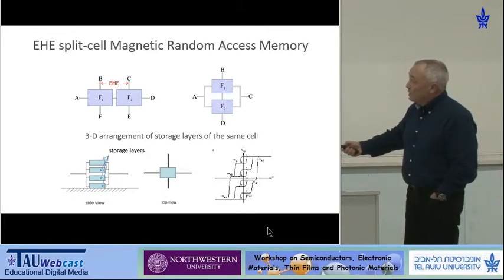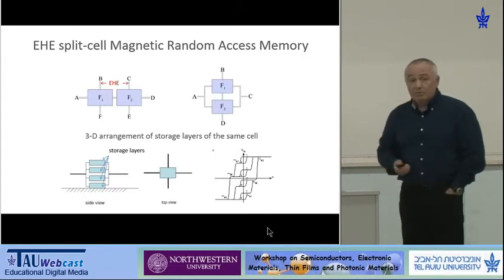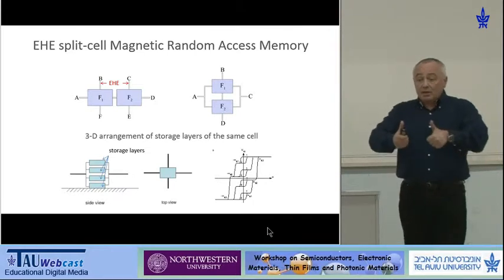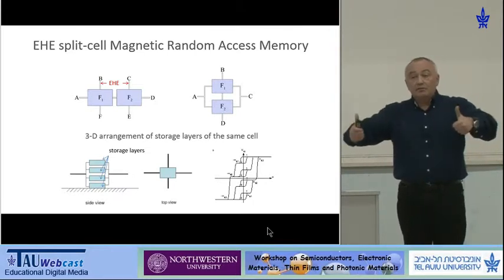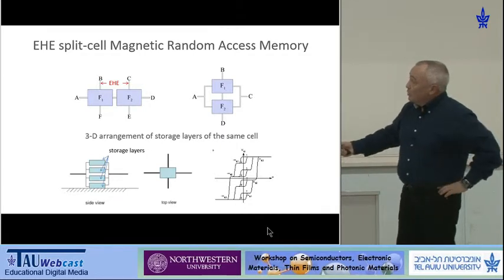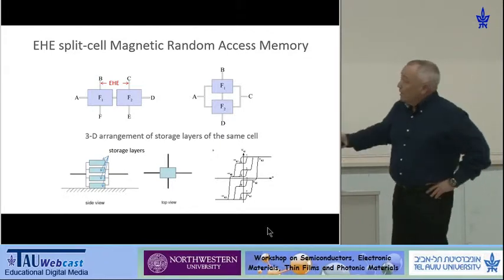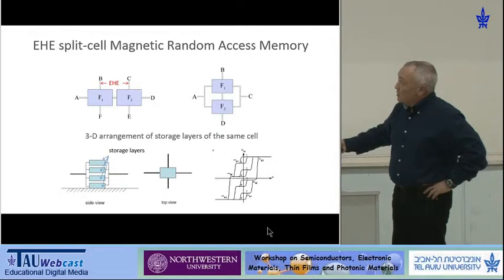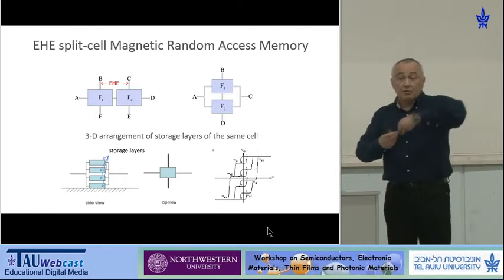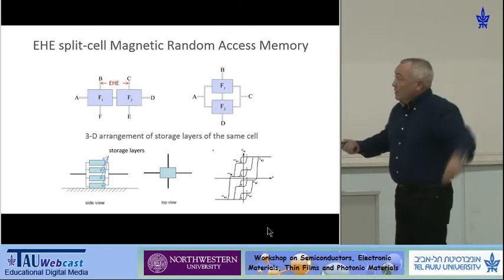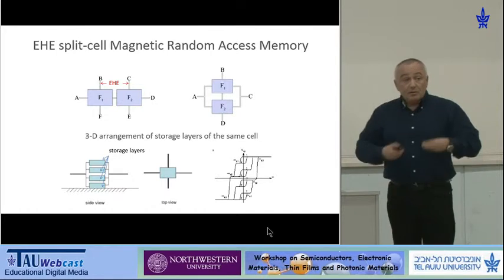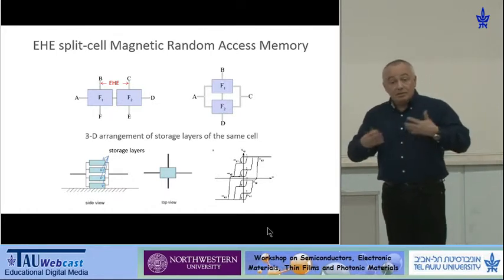Imagine that you have one magnetic dot and the second magnetic dot. Both of them have perpendicular magnetic anisotropy, but with different, let's say, coercive field and magnitude of the phenomenon. Now you connect them electrically, and you measure voltage between this point and, say, this point. Then what you have is Hall contribution from here, Hall contribution from here, and resistance transition from one to the second. The signal that you will measure will in fact include all these contributions.